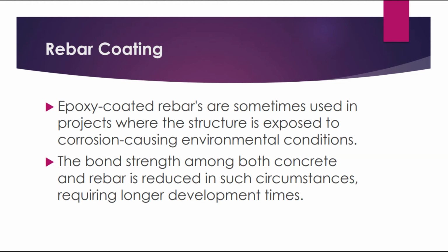Rebar coating. Epoxy-coated rebars are sometimes used in projects where the structure is exposed to corrosion-causing environmental conditions. The bond strength between both concrete and rebar is reduced in such circumstances, requiring longer development lengths.